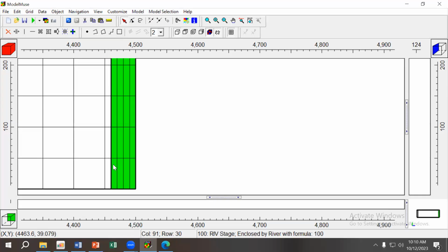Before I tell you what the area is, let me tell you what the hydraulic conductance is. This is my Darcy. If I write it like this, Q as a function of delta H, and again delta H here is the head in the river minus the head in the aquifer. The head here minus the head here.